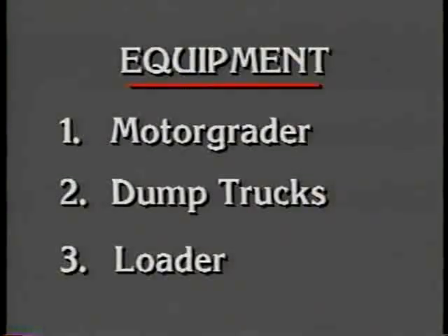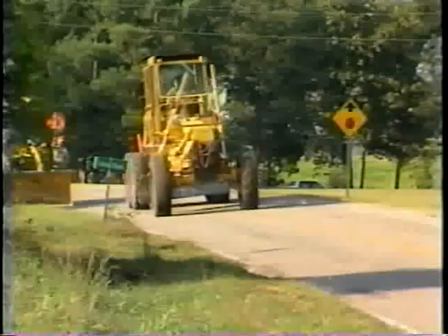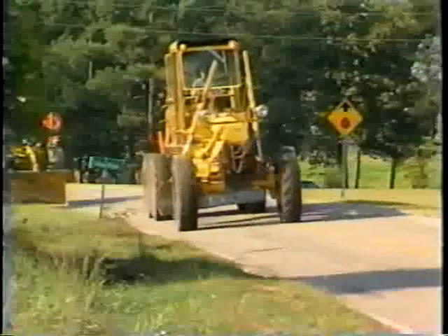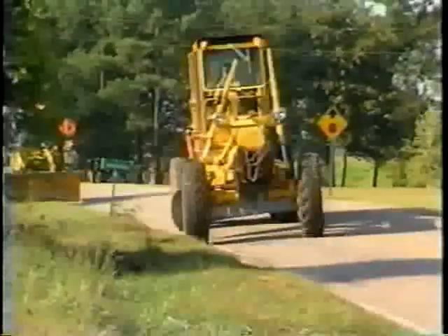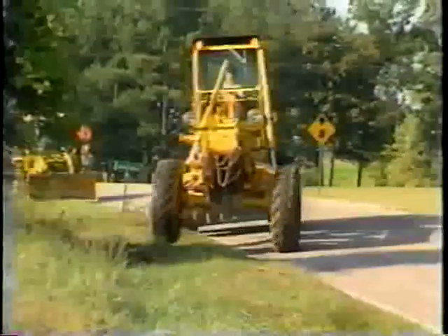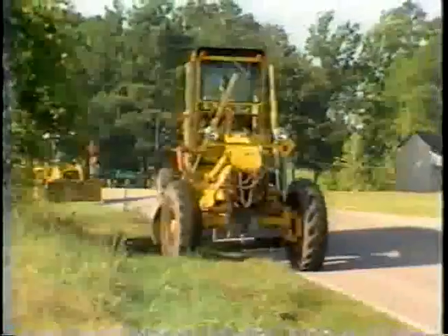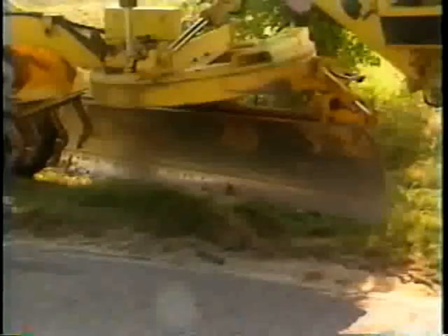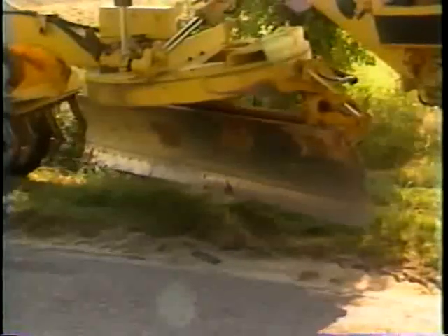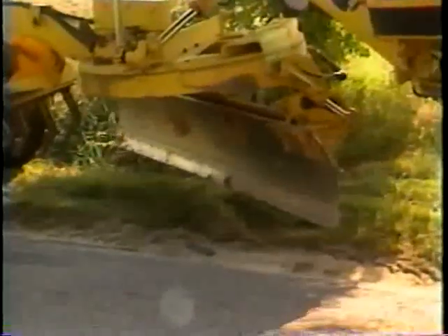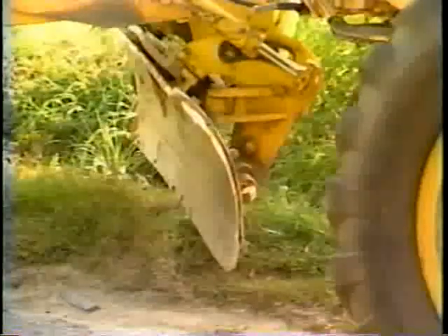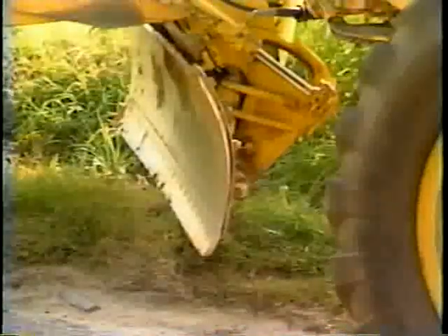The equipment required to perform high shoulder repair includes a motor grader, dump trucks, and a loader. If the shoulder is very hard and densely compacted, loosen the material with a scarifier attached to the motor grader. Position the grader on the shoulder. Angle the blade at approximately 45 degrees. The blade pitch is upright or tilted back slightly.